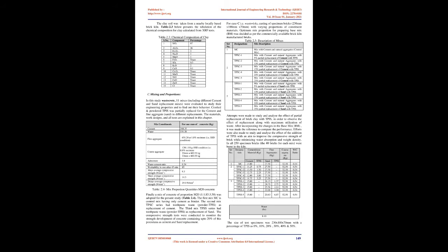2. Materials and properties. A. Research methodology. Keeping all this in view, the objective of study, the methodology was decided to study the waste and behavior of concrete while adding waste with different proportions in concrete mix, i.e. 0%, 5%, 10%, 15%, 20%, and 25% by replacing cement in case A, replacing sand in case B, and in case C clay was replaced with TPIS as 0%, 10%, 20%, 30%, 40%, and 50%, then testing for compression strength, water absorption, etc. as shown below.